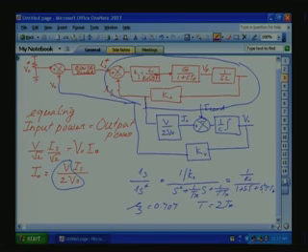See, these higher frequencies will be much beyond the response range of the current loop. So, we can approximate this current loop, Is divided by Is star, to design our voltage loop. This is 1 by Ki divided by 1 plus ST. We know T is equal to 2 Tr in general.